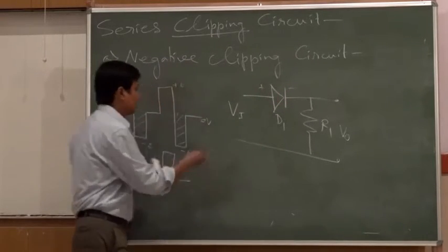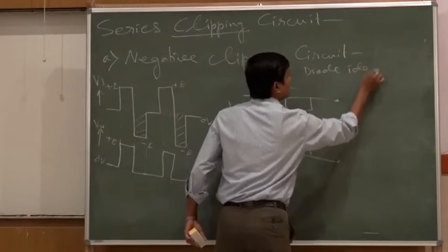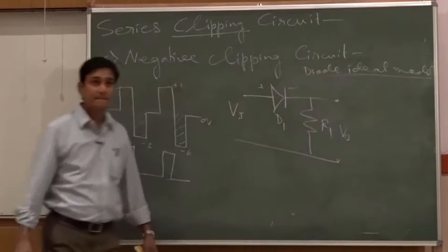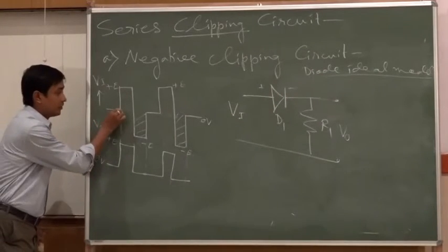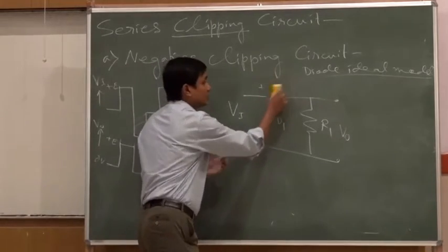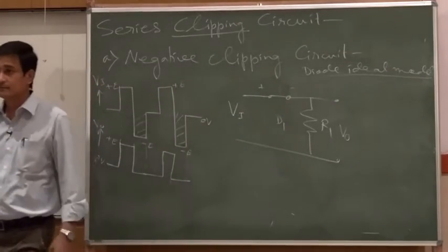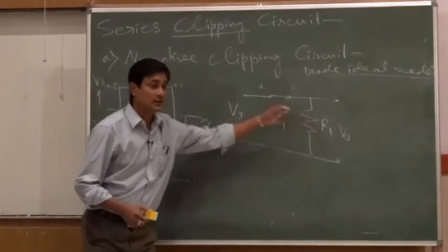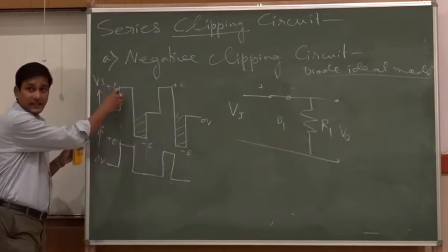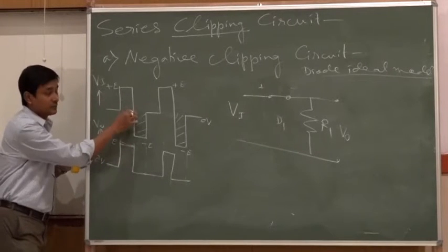If I consider the diode ideal model, if the voltage goes beyond 0, in that case I will see the equivalent circuit is just like a short. So, what is the output voltage? Purely this Vi which I have applied, which is plus E. So, I will get plus E till this point.